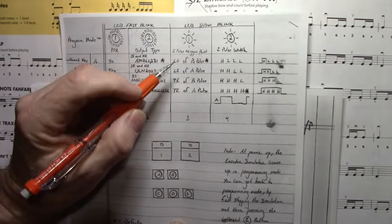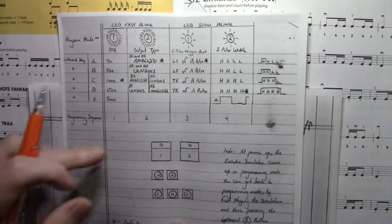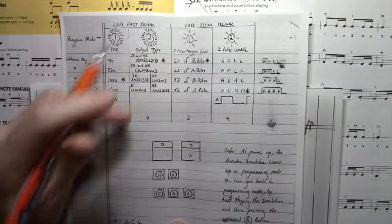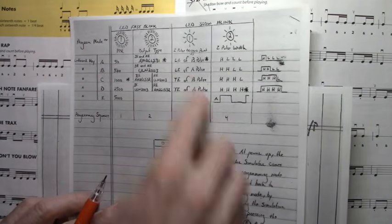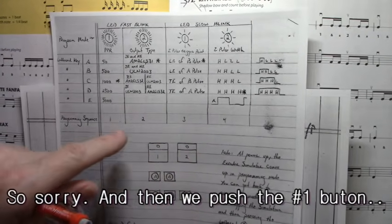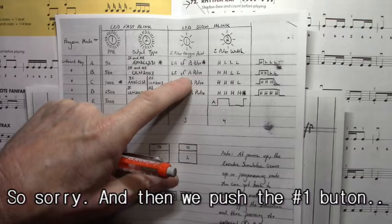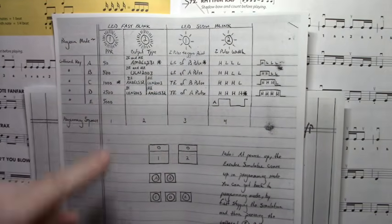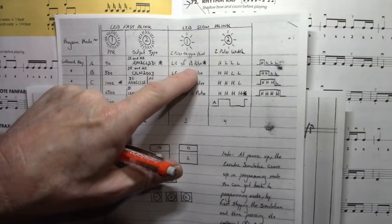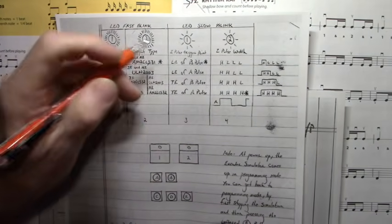And we want to set the leading edge of the A pulse. That's where the Z pulse will trigger, on the leading edge of the A pulse. So we push the B button again, and then we push the number 2 button. And that will set the trigger of the Z pulse to fire on the leading edge of the A pulse. But if you want the default, just push that button right there and it will be the leading edge of the B pulse. That will be the default when that Z pulse occurs.